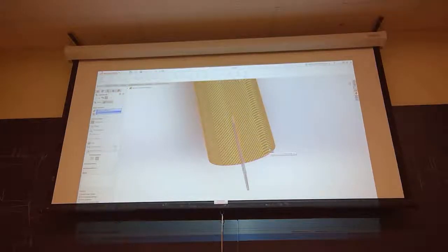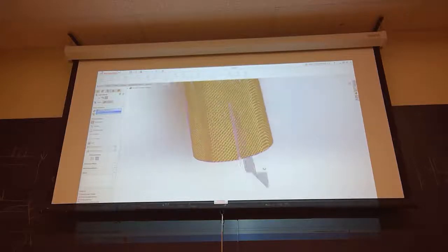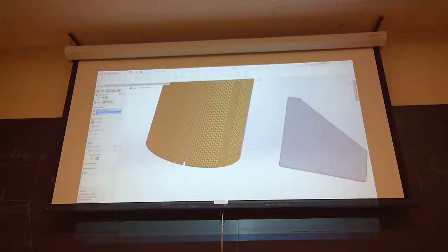Does that make sense? Alright. What type of mate? Coincident. He made it the side of the slit to the side of the face. Yep. And again, it may be flipped, so you need to make sure you align it so that the top of it is going to go inside of the slit, okay? Basically, but it works.